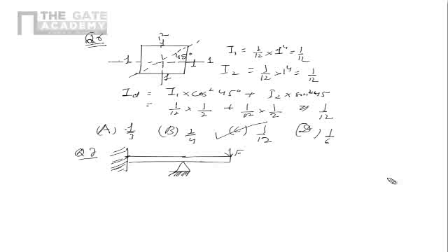We know that the deflection equation is given by d square y upon dx square is equal to M upon EI. Here, because the force is fixed, the value of the force is fixed as well as the location, so for a particular location of the beam at a distance x from the center, it will fix the moment also.